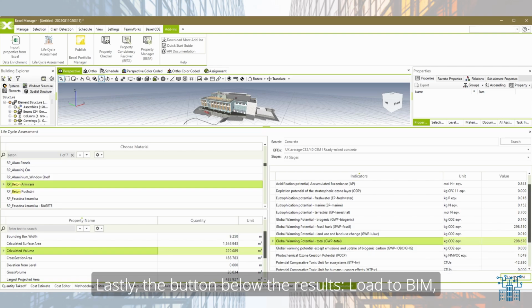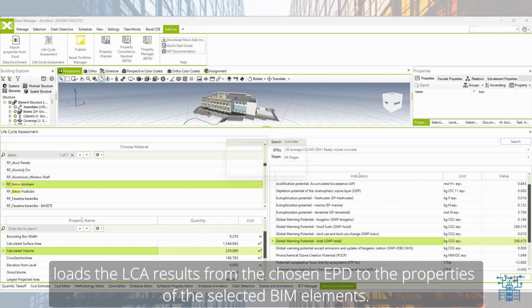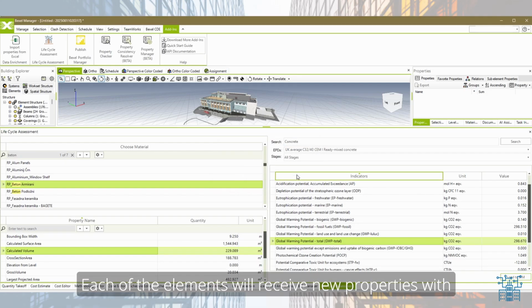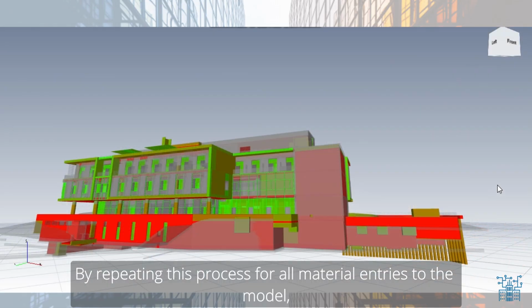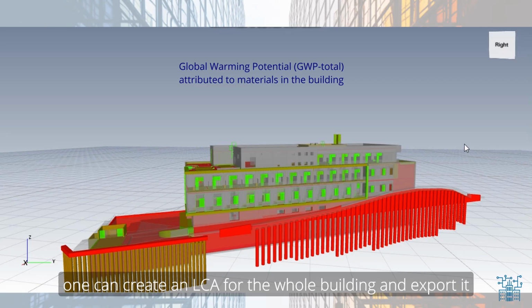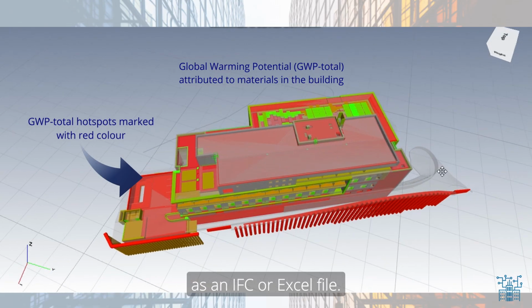Lastly, the button below the results, Load to BIM, loads the LCA results from the chosen EPD to the properties of the selected BIM elements. Each of the elements will receive new properties with values of the EPD indicators multiplied with the quantity of the material in the building in the selected measuring unit. By repeating this process for all material entries to the BIM model, one can create an LCA for the whole building and export it as an IFC or Excel file.